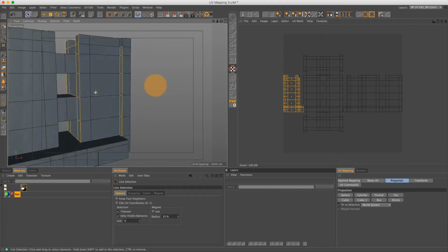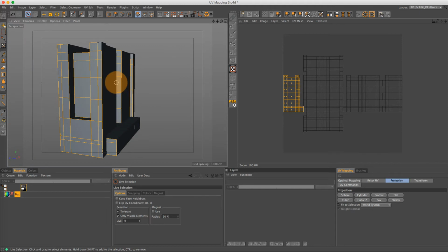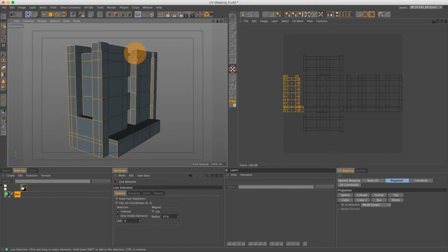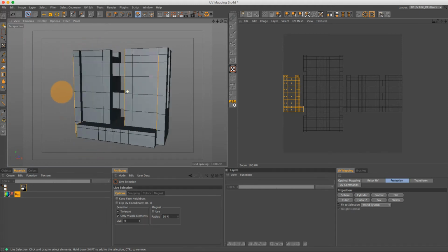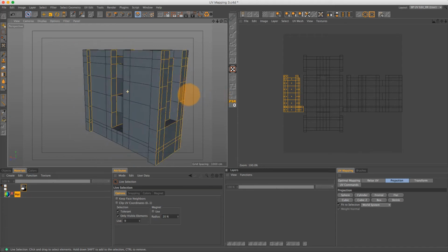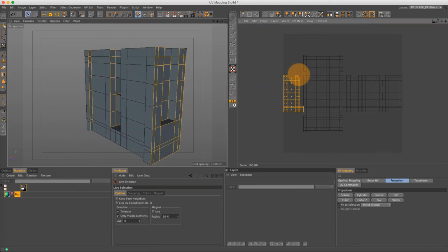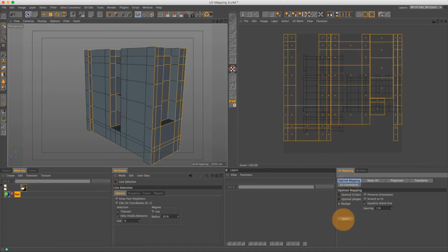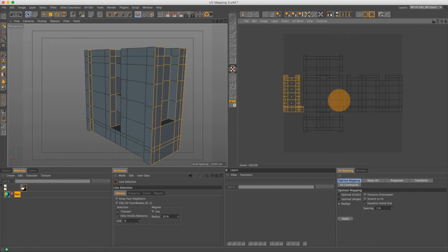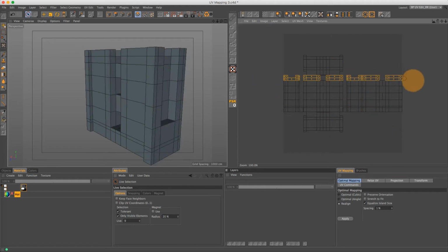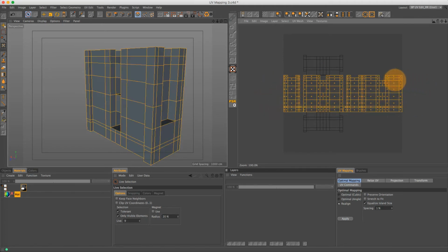Truth is that it's just projecting on the left side, and it's hitting all the normals that are facing the right side. So these pieces are not actually connected. So if I select all these and I do an optimal map and I do a realign, you see how we get this really crazy distorted thing. And when we're doing buildings, we want to keep them all horizontal at the same angle, so that when we apply our texture, all the windows line up, all the tiles line up, all the blocks line up.